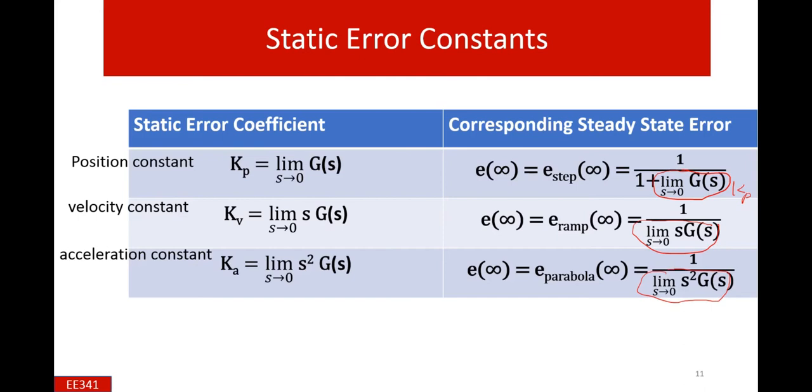But now our concentration is focused on the G(s). If we change the type of system, for example this is type 0, then definitely we find some constant value. If it is type 1, the answer will be different. And similarly, if it is a type 1 system, then this s will be cancelled out with that one, and overall we find some DC value or constant value.